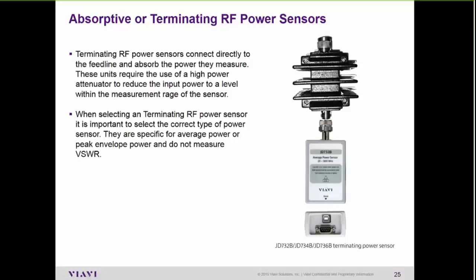You also need to use the attenuator that's included in your kit and take that into account for the signal drop. So I think these are a 40 dB, 50 watt attenuator. So it reduces the signal power down to a level where your test set can read it directly. You can also use this attenuator with the spectrum analyzer type of power measurement directly on the test set itself. But again, you need to drop the power down to where it's in a range that your test set can handle. The max power for the test set is plus 25 dBm, so a little less than 1 watt.